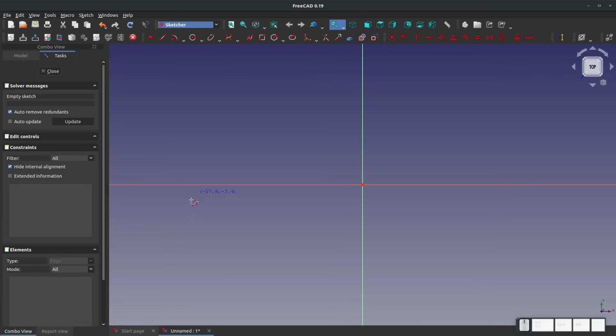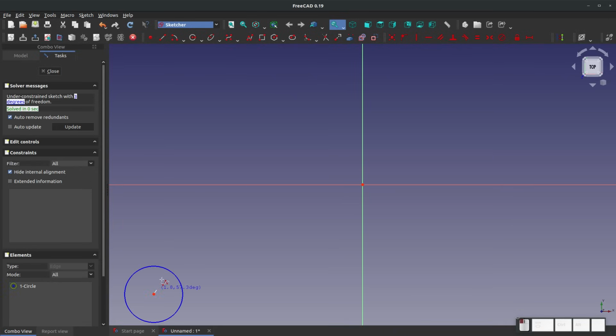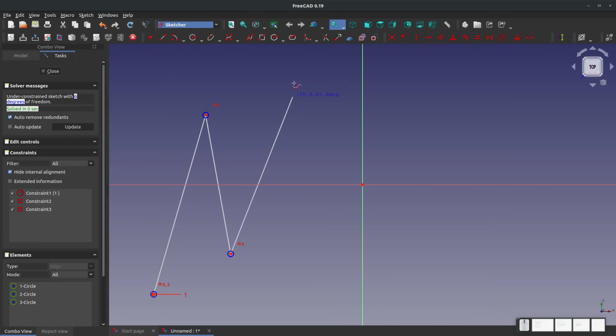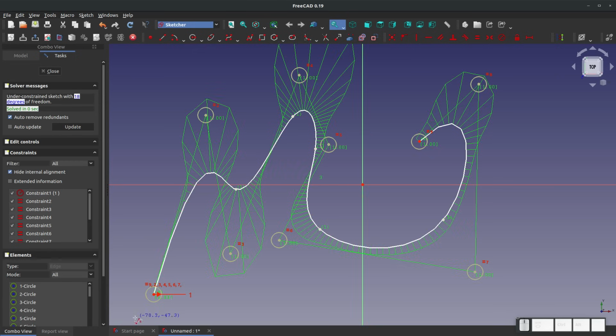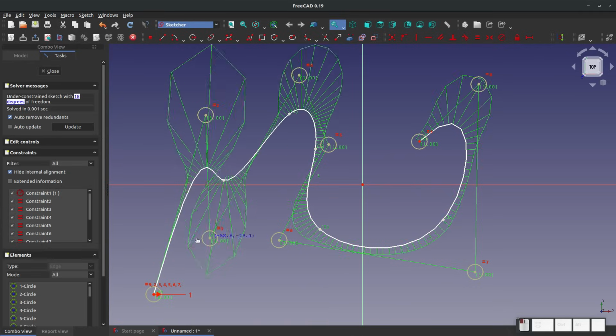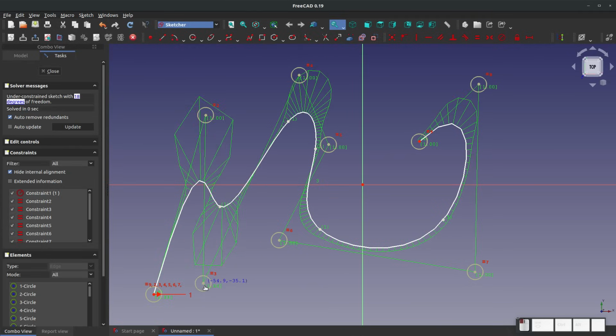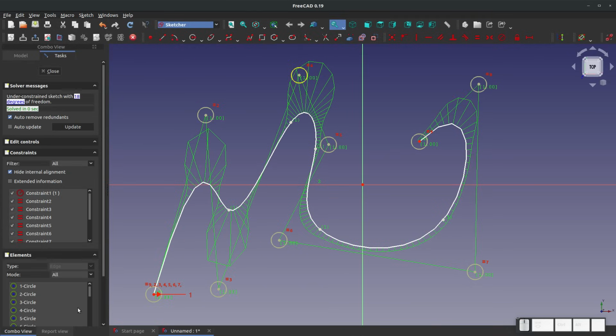Let's go with a spline. This is kind of a tough one for beginners, but with my spline I can click in many points in kind of whatever sequence that I want. And then if I hit the escape key once, it draws a spline that is relative to the points that I've drawn, right? So I can drag these points that I've clicked and it changes the profile of my spline. This is kind of hard to use and kind of hard to define, but it's extremely useful if you need non-constant radius geometry that works pretty organically, you know. But again, a little bit hard for beginners.